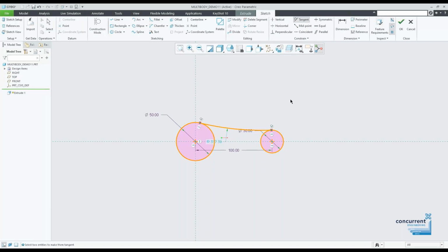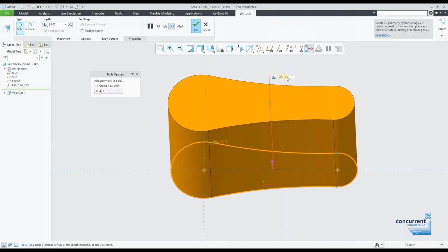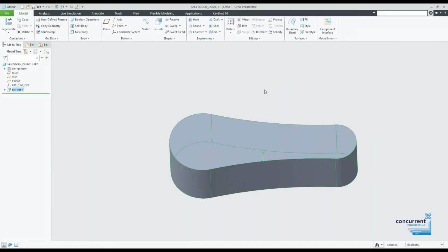And then use the newly developed mirror, so I don't need to specify a centre line as such. I can use the existing geometry and then remove the material I don't need. Okay, it's looking good. I'm going to set that with a height of 40 mm. Nice.